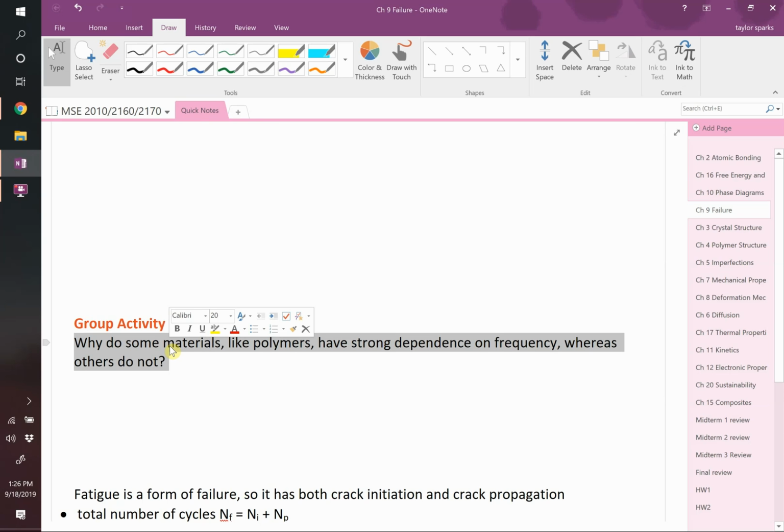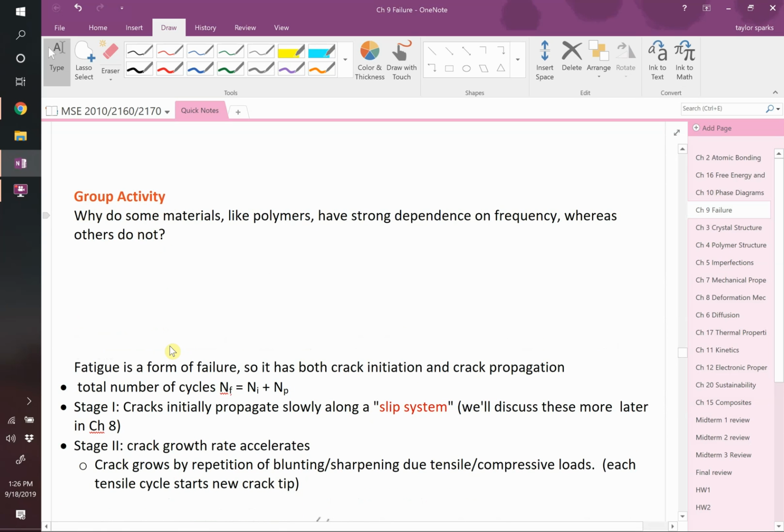And you end up with it heating up a little bit, right? And in polymers, when you heat it up, because they melt at such low temperatures, then you transition from a different deformation mechanism, basically. So metals and ceramics melt at much, much higher temperatures, and so they're not as prone to this problem. Okay? Hence, polymers are more likely to be frequency dependent. So yet another thing you have to account for. Not just strain rate, not just temperature, but now frequency dependence if you really want to get this thing right.